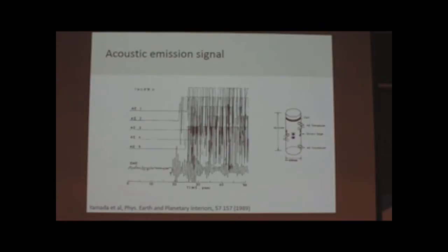So for example, if you have a piece of stone, and you apply a great deal of pressure, if you apply enough pressure, you can cause the stone to break. And when it breaks, it's a sudden kind of event, and you get catastrophic failure. And what happens is if you've got transducers, strain gauge, piezo transducer pickups, you can measure acoustic energy. And this is time in microseconds, so 10, 20, 30, 40 microseconds. And you get these very large amplitude vibrations that follow fracture.